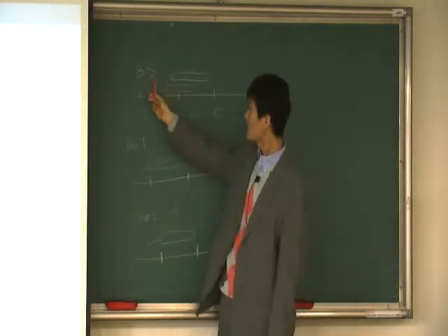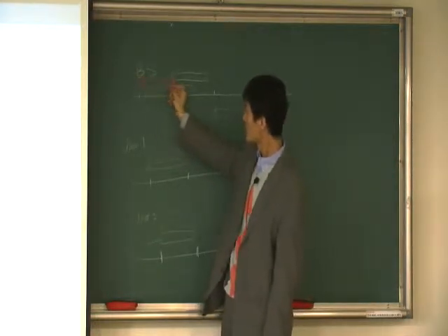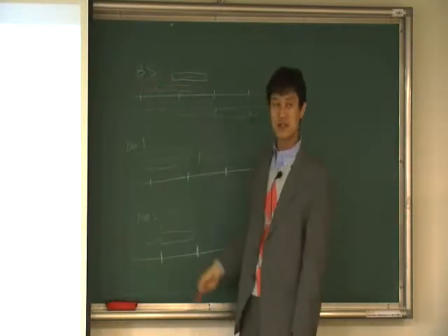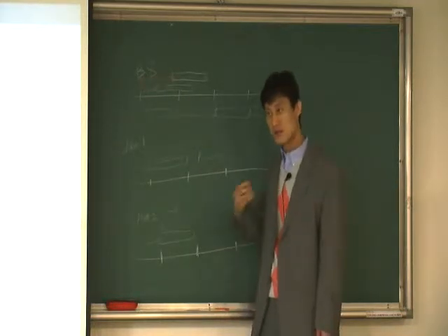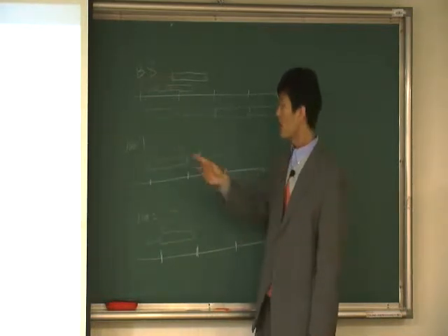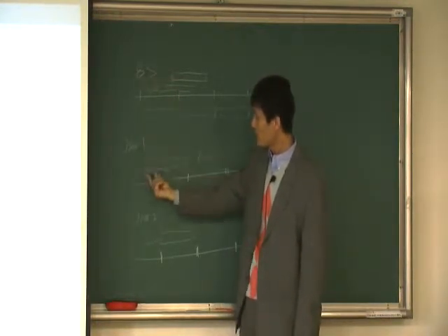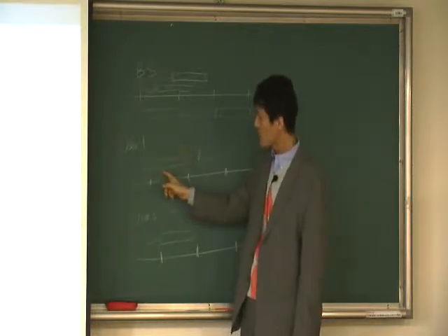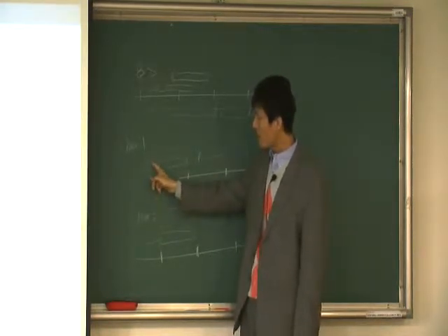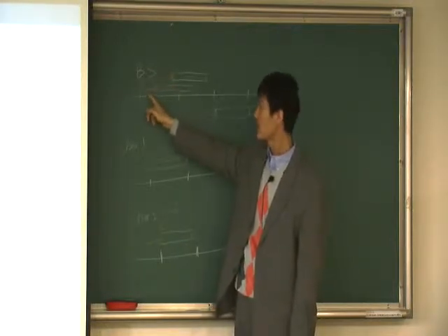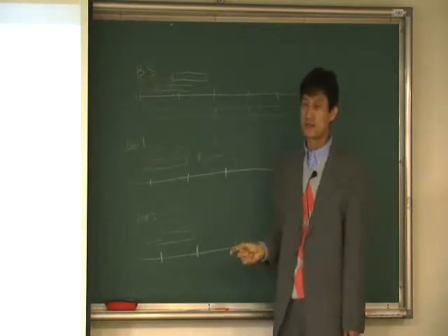And then the base station now knows this much delay. And what is this delay? This delay is actually the round trip delay. Because the base station originally transmitted certain data. That data experienced some propagation delay and then was received by user 1. And now it's synchronized. And based on this synchronization, you transmit the random packet. That packet again experiences another propagation delay over uplink and is received by the base station. So this delay is the round trip delay.